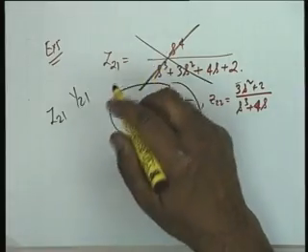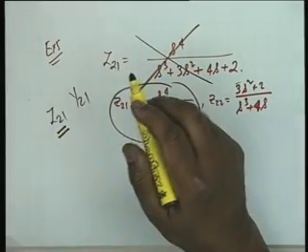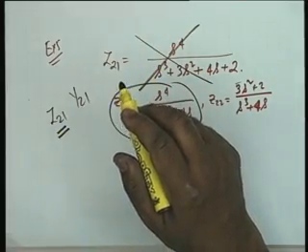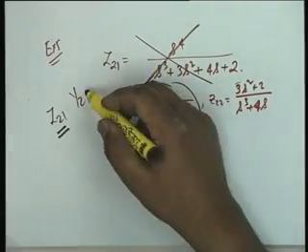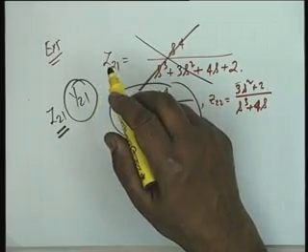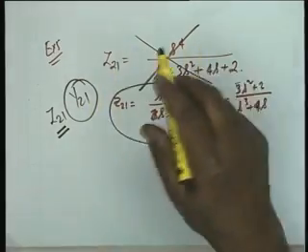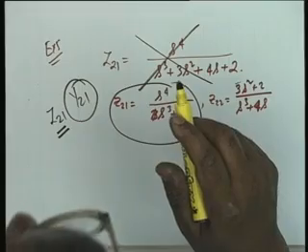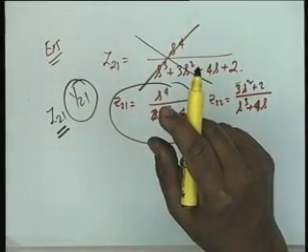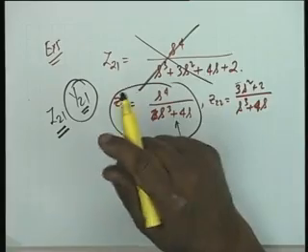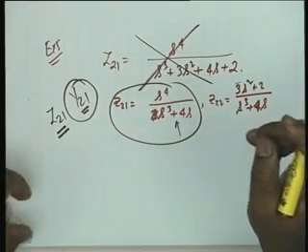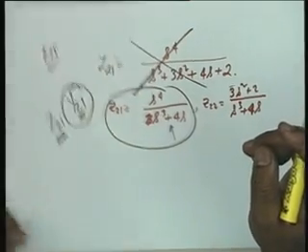If it is a current generator, that is, if it is a Z21, then the last element must come in shunt, whereas if it is Y21, the last element must come in series. Output will be the current. In Y21 the output is current, in Z21 the output is voltage. Okay, right. Now this is one method of synthesis.